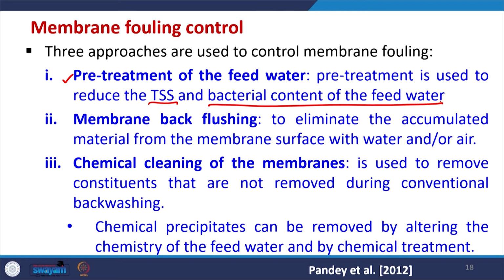If it is done, we will be able to avoid more suspended particles passing through the semi-permeable membrane, so the fouling will be reduced. Also, if the bacterial content is removed beforehand, bacterial growth will not be there, and this way we can avoid the bacterial growth which ultimately blocks the membranes.